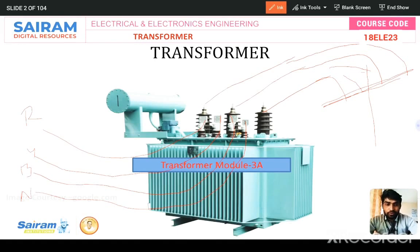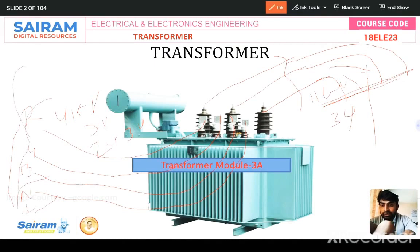This is the input: 11 kilovolts, 3 phase power supply. And the output is 415 volts, 3 phase, or 230 volts. Either is possible, single phase as well as 3 phase. If you connect one phase to neutral, you will get single phase. If you connect R, Y, B and neutral, you will get 3 phase power supply output. Keep it in your mind. That's why we are using a transformer.